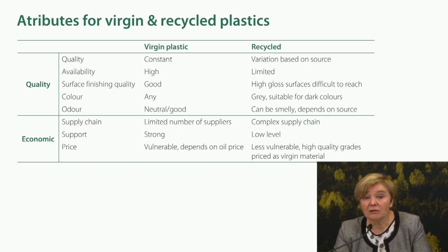While in recycled plastics, because of the changing materials, usually both MSDS and TDS are of lower quality or not available at all. So when developing a new product, you should rely more on your own knowledge and on the properties of the material you have been testing than on the material properties provided by the supplier.